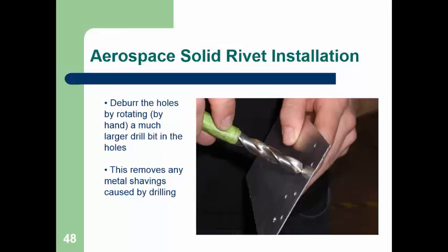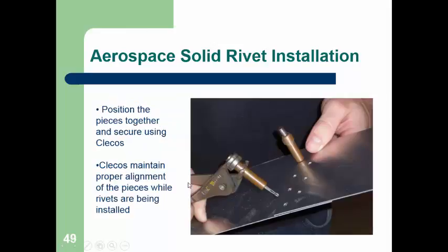It's a huge expense, a huge part of the cost of actually assembling an aircraft, because you have to be very, very careful to retain the strength of your fastened joint by making sure that the two substrates that you're fastening are in intimate contact. They don't have drill shavings that are propping up one side or whatever.